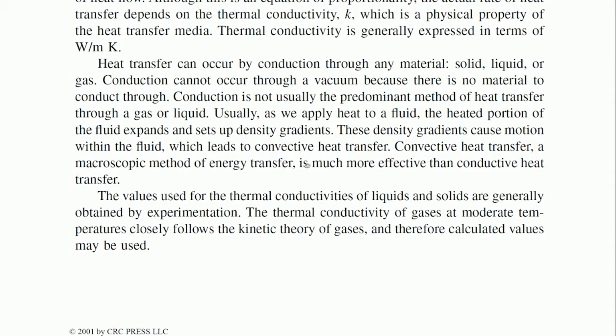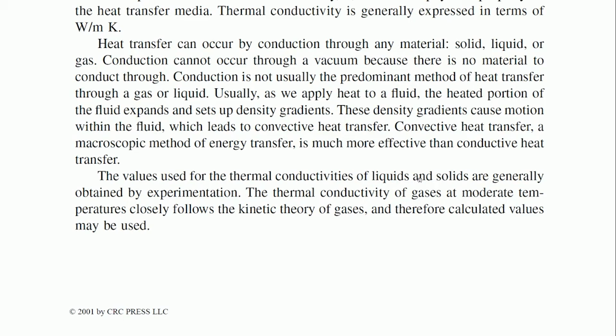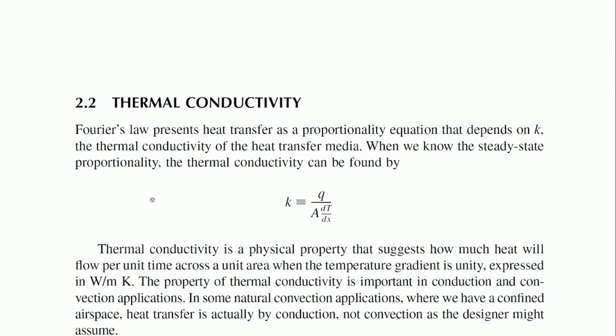Convective heat transfer, a macroscopic method of energy transfer, is much more effective than conductive heat transfer. The values used for thermal conductivity of liquids and solids are generally obtained by experimentation. The thermal conductivity of gases at moderate temperature closely follows the kinetic theory, therefore calculated values may be used. Most important here, this is what I wanted to tell you, the issue is about experimentation. Without experimentation, or trying to establish the actual conductivity coefficients in actual use, trying to extrapolate may not be that effective or useful, because even surface characteristics and the way things are mounted and the way things are oriented, all of them seem to make a tremendous amount of impact.